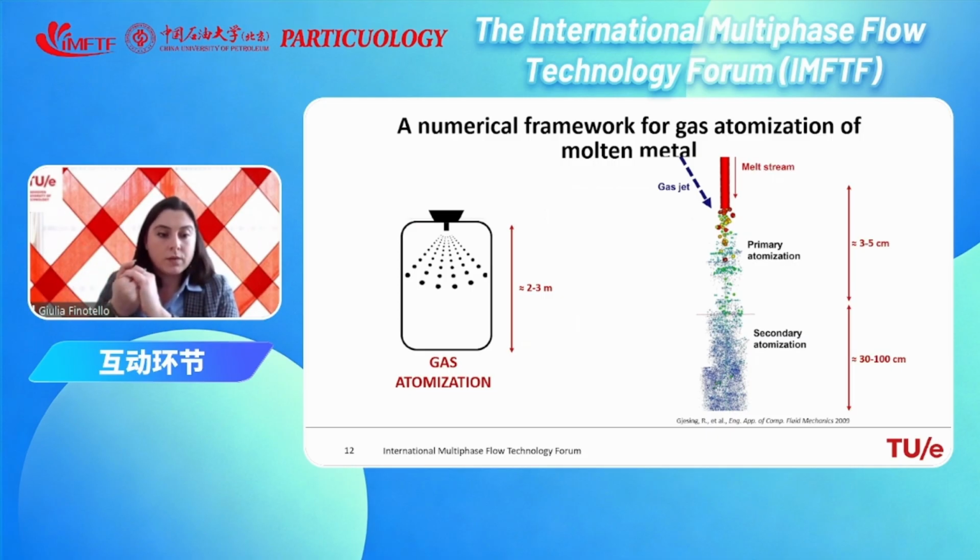And depending on the configuration of the nozzle and the operation of the nozzle, what they found in industry, which is very problematic, is that there could also be some clogging due to very fast solidification of the melt, or part of the melt, close to the nozzle. And of course, that's why it's very important to tune the conditions as well as use a special configuration of the nozzle. That's why close-coupled nozzles are used, to prevent the clogging of the nozzle due really to this solidification of the melt,